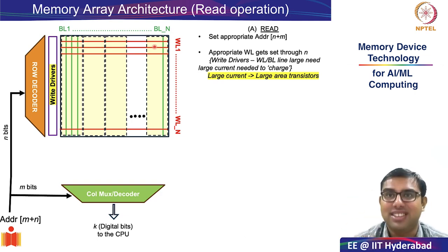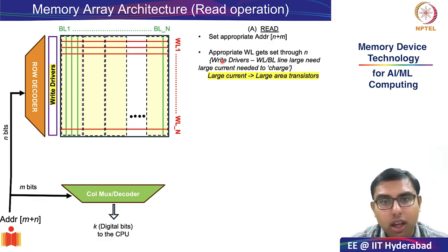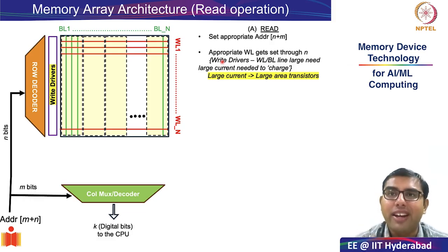So here we are going to change the terminology of applying some value to the word line. Earlier, the terminology we were using was that we assert the word line. When we use the terminology assert, we assume that the word line consists only of a resistive element. As we just discussed, at high frequencies and in scaled devices, that may not necessarily be true, and therefore we use the word charging.